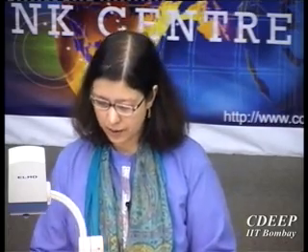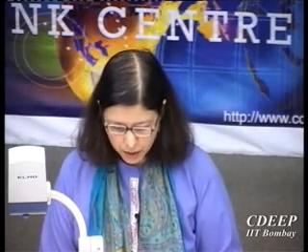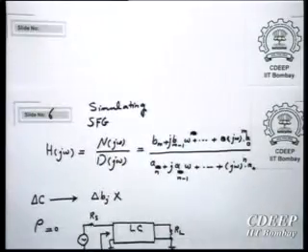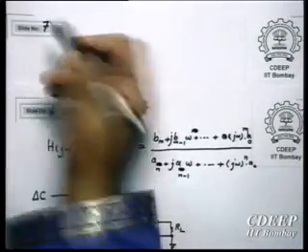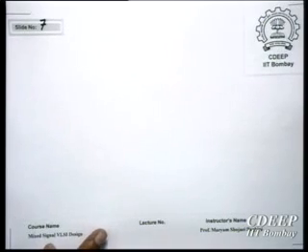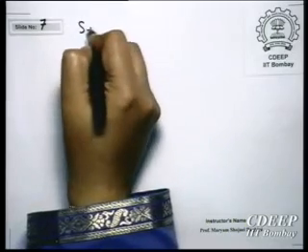It is one thing which we care about when we talk about on-chip variations and on-chip implementation of active filters. So to be able to compare different architectures with respect to sensitivity to process variations or anything else, even if it is a discrete filter, now we are talking about on-chip variation, a parameter is defined called sensitivity.